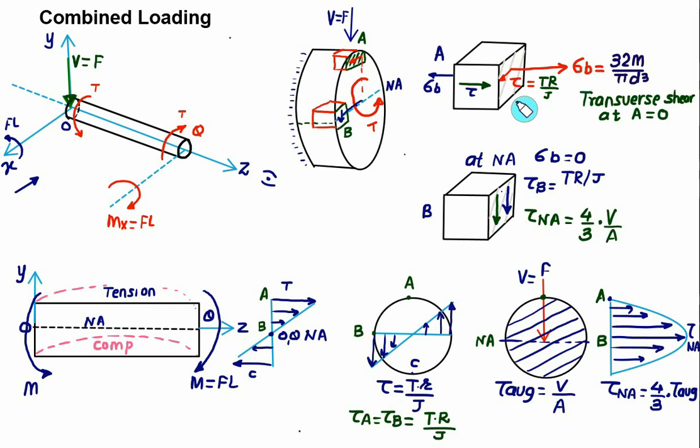We know the sigma maximum and sigma minimum. Sigma maximum and sigma minimum is given as (sigma x plus sigma y) by 2 plus minus under root of ((sigma x minus sigma y) by 2) whole square plus tau xy square. So the shear stress and the maximum normal stress will be maximum at point A, and therefore the critical state of stress is represented by A, not at B. So our design is based on the critical state of stress, that is at point A.